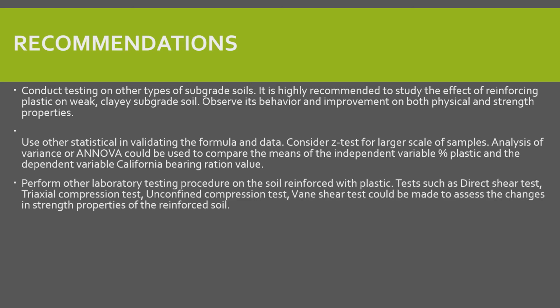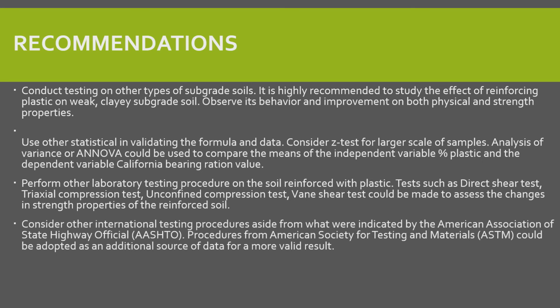It is highly recommended to perform other laboratory testing procedures on the reinforced soil, such as direct shear test, triaxial compression test, confined compression test, and vane shear test that would be made to assess the changes in strength properties of soil samples. It is also good to consider other international testing procedures aside from what is indicated in AASHTO. Procedures from ASTM could be adopted as an additional source of data for a more valid result.